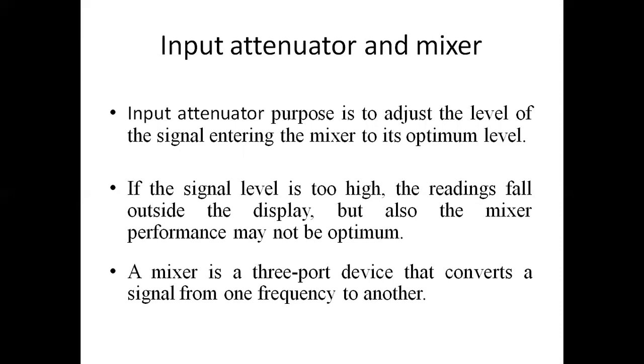If the signal is too high, the readings will fall outside the display, and the mixer performance may not be optimum. As we know, a mixer is a 3-port device that converts a signal from one frequency to another. So this input attenuator and mixer setup is very much needed as we are using the mixer component here.